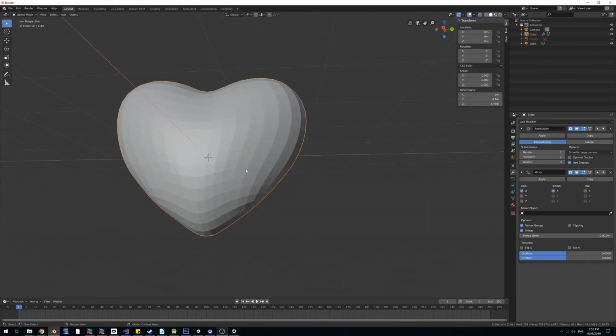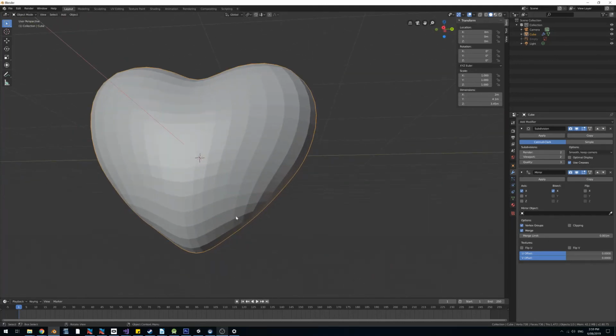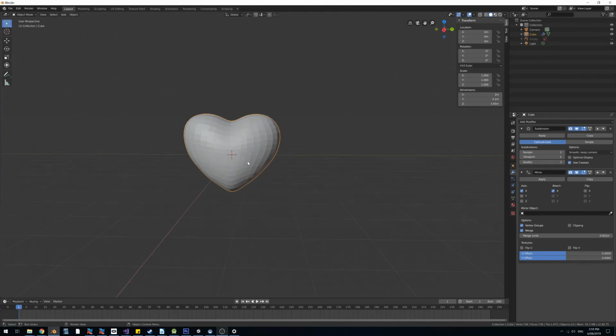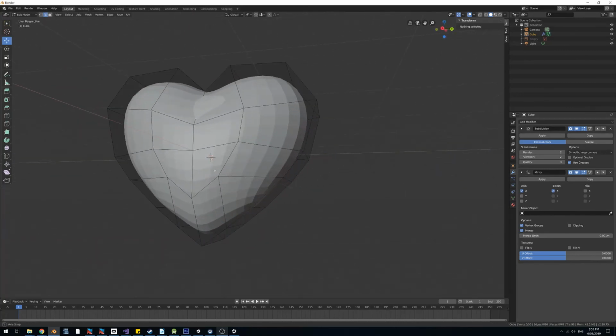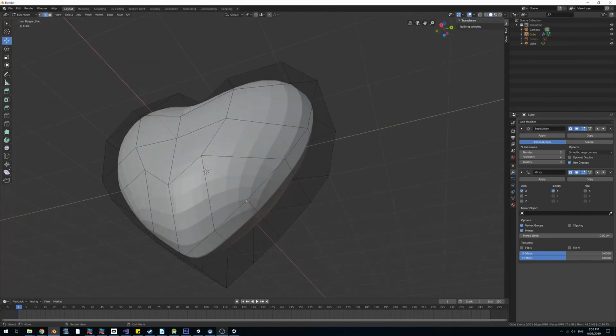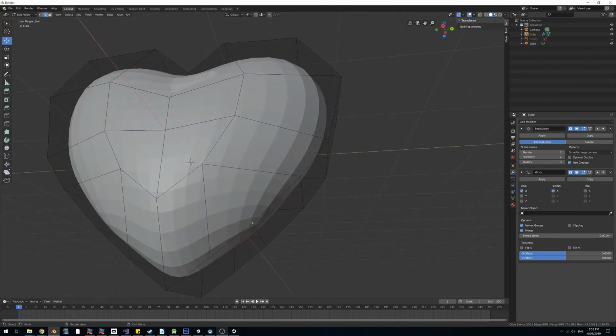And I don't think I like that. I want this to be a much cleaner mesh because when we look at it, we see a bit of a pinch. So what I'm going to do now is I'm going to go back into Edit Mode and fix this mesh up. And if we look carefully at what's happening, we can see that there's a bit of an edge here that terminates. There's this point where the edge follows and then suddenly it stops. And where it stops, the mesh has got this pinch point.